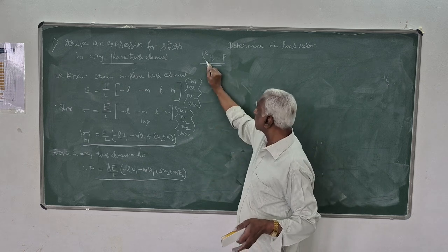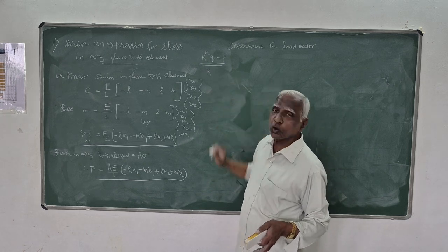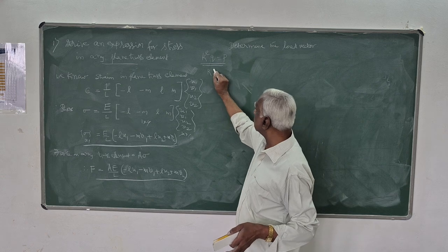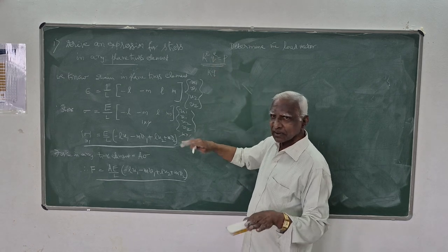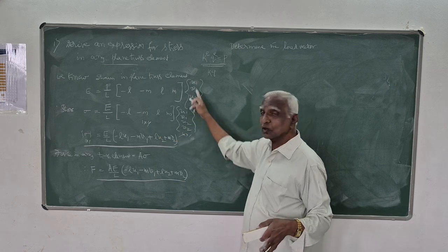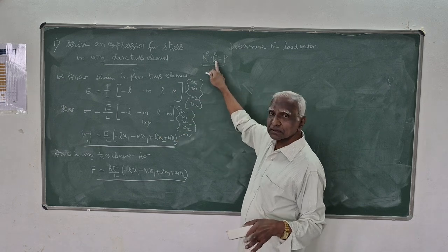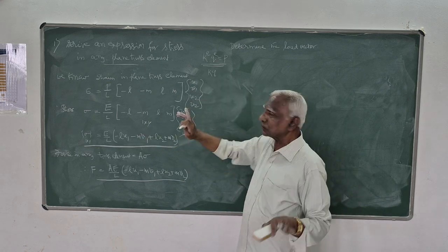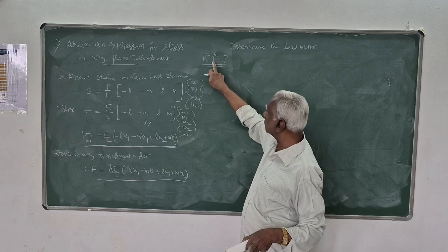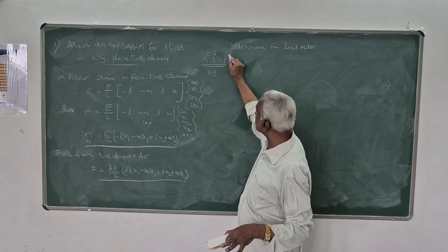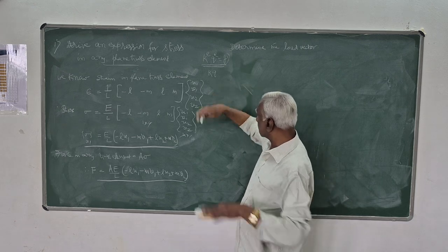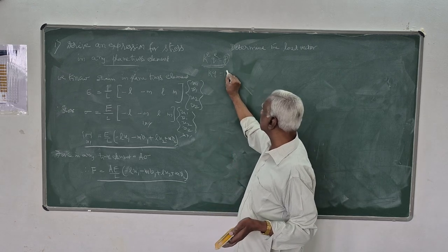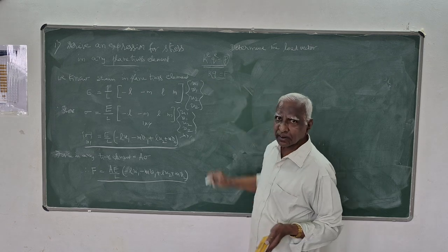If you take this KE, you convert it into global coordinates, K into global displacement Q. Here you saw, these are all the global displacements. Element displacement is just Q1, Q2. If you take Q1, Q2 and KE, then this is the load vector. And in the global direction, KQ is equal to the force vector.